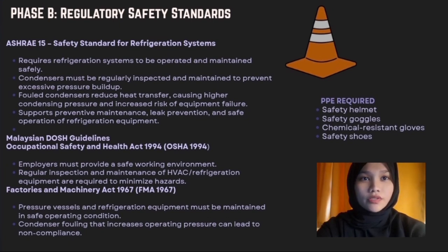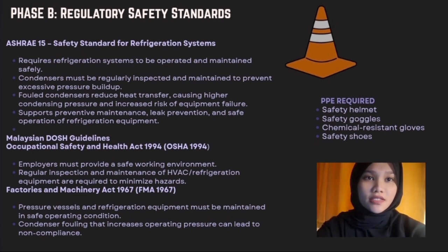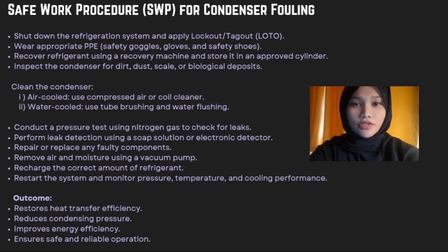In Malaysia, both the Occupational Safety and Health Act 1994 and the Factories and Machinery Act 1967 require employers to maintain refrigeration equipment in safe operating condition. To ensure safety during maintenance activity, personal protective equipment such as safety helmet, goggles, gloves, and safety shoes must be worn. The slide shows the safe work procedure for handling condenser fouling.